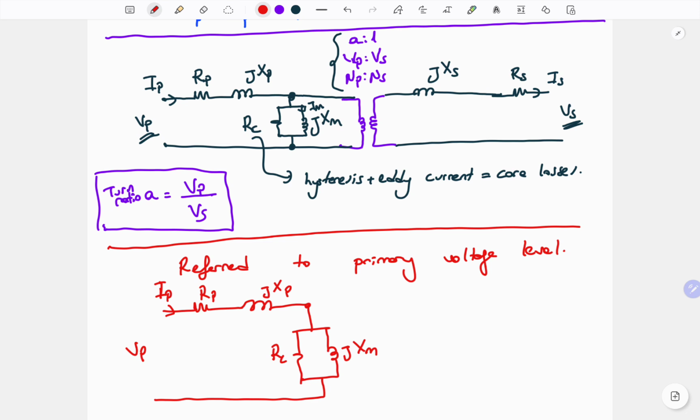For these components, we can transfer them to the primary side. We want to eliminate this middle part, the conversion part. So we can use one reactance and one resistance, but we change their places. So we will call them primes, and we must keep the equality of the previous equivalent circuit and this one.